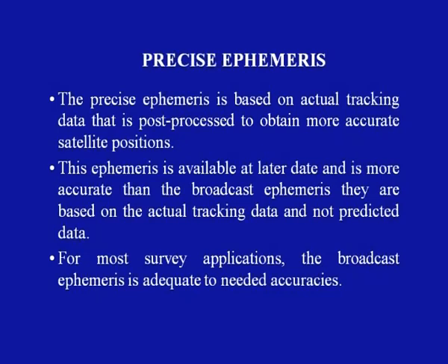Thereby, any user who is interested in obtaining very precise point position or coordinates of a point must use the precise ephemeris rather than the broadcast ephemeris, which is available on a predicted basis of the satellite data. For most survey applications, the broadcast ephemeris is adequate for the needed accuracies.